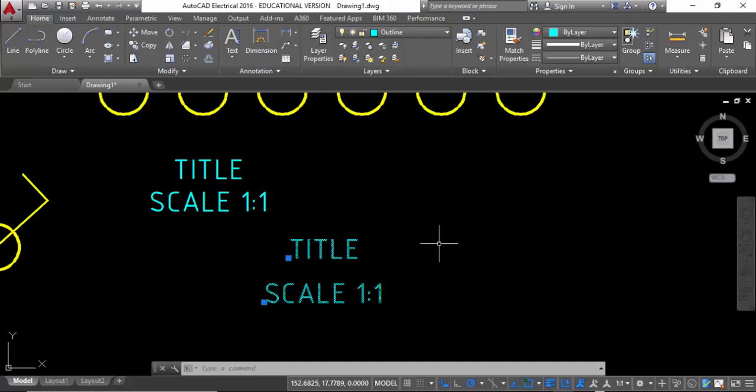They don't enjoy that, so don't do that. Rather utilize your multi-line text, which will be consistent, unless you want to place multiple texts all over the show, say for instance 1, 2, 3, 4, 5, then I will use my single line text to do that.